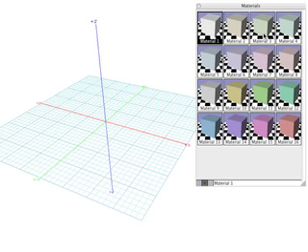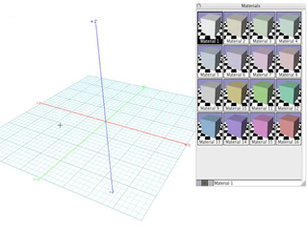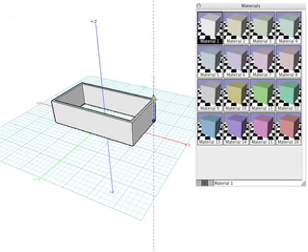When an object is first created, bonzai3d assigns the active material to that object. For example, we'll create a 3D solid wall by selecting the Rectangle tool and the 3D enclosure icon. And when we create that object, you can see that since material 1, which is a white generic material, is active, that's the color that's assigned to the object.